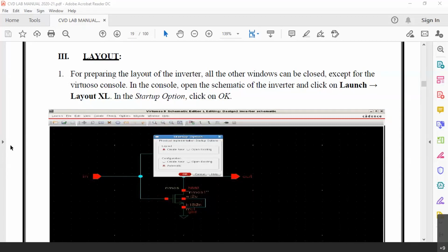But when you perform the layout simulation, for example, then you have the physical transistor with all its area definitions, which means when we simulated the circuit diagram, we did not have the complete RC model or the complete physical model of the transistor.